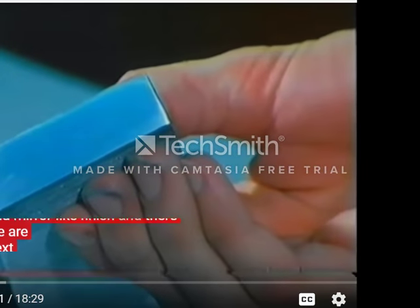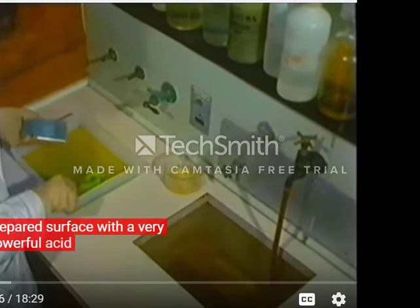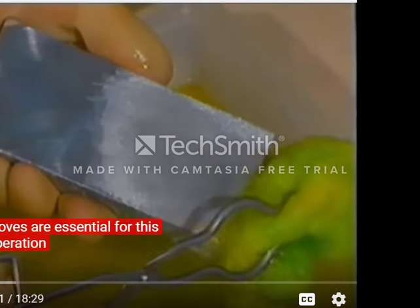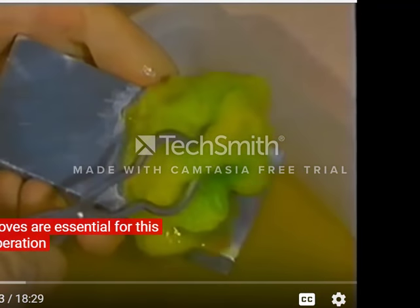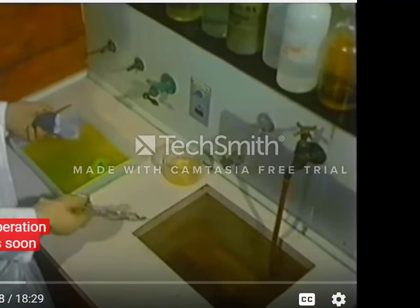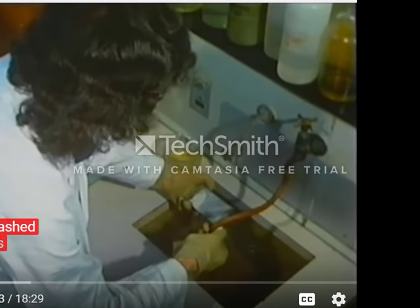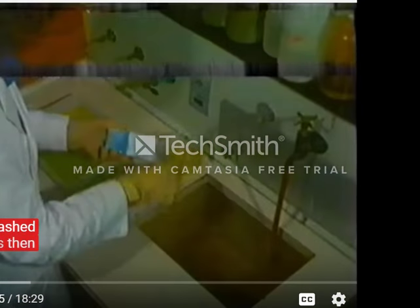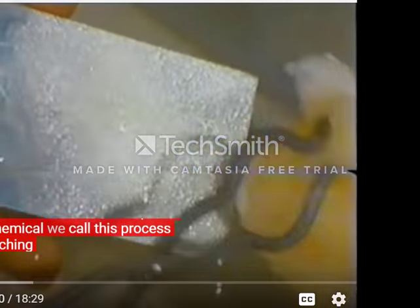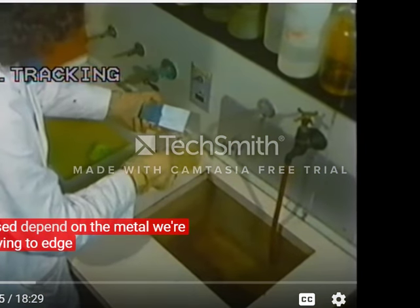And there we are. Next, we treat the carefully prepared surface with a very powerful acid. Gloves are essential for this operation. As soon as the acids have time to react, the metal must be washed. It's then given a second treatment with another special chemical. We call this process etching. The particular chemicals used depend on the metal we're trying to etch.